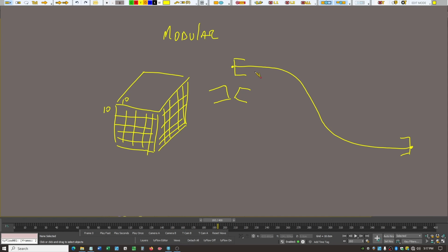Now there's two ways you can kind of think about track design. At some point the marbles have to continuously run downhill or they're not going to run, right? So the way I'm going to do it is I'm not going to have this angle that joins together and everything is angled. The way I'm going to handle my track design looking from the side is there's going to be a short horizontal section, then whatever angle down, and then followed by a short horizontal end. So we have a horizontal beginning and a horizontal end so that we can get this perfect alignment from each modular track section. So let's make our first drop.